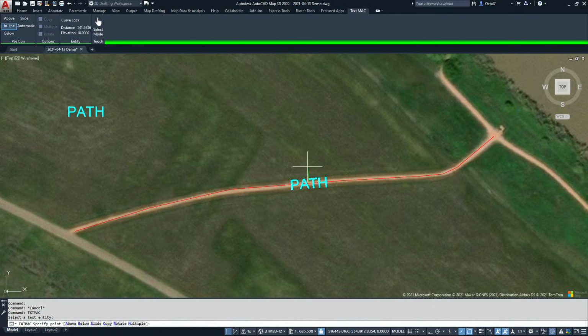I find this comes in a little bit handy when labeling contour lines, and I have contour lines or maybe other geometry at different elevations, and I want to make sure I'm on the correct contour line with inserting that label. So I know that, okay, I've got my contour label says 750 meters or something like that, and I want to make sure I'm putting it on the correct line, right?